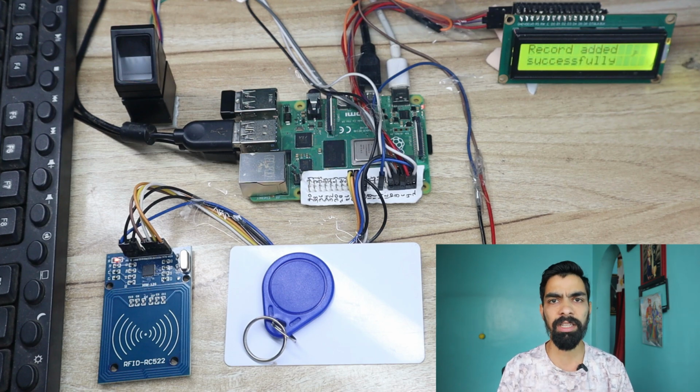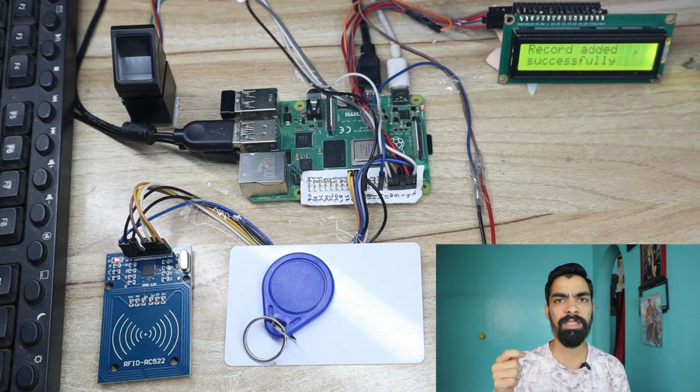So if anyone selects this first section, then on the LCD it will show please give the lecture name. Once you type the lecture name through the keypad, then automatically an Excel sheet with that lecture name is created in our database. After that, it asks you to scan the card. Each and every student has his identity card. Once the student scans his RFID card through the RFID module, if the student's RFID data is available in our database, then it will ask you to scan your finger. Once the student scans his finger, attendance is automatically taken for that lecture and the attendance of the student is stored in our Excel database. Okay. Now this is the first part.